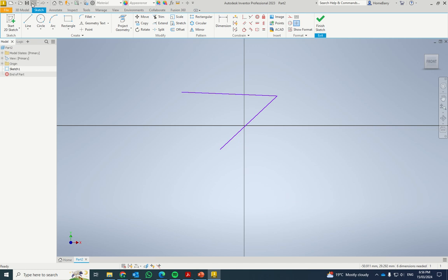Similarly, if I undo that, I can say I want the middle of that line to be coincident with the end of that line. It's a bit hard to control because you can't really predict which one it's going to move. But as long as that constraint is satisfied, I can still move my lines around.